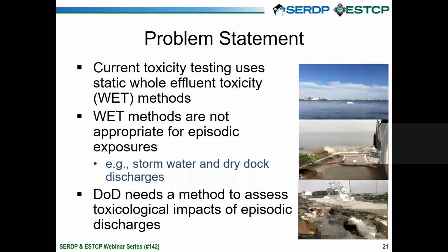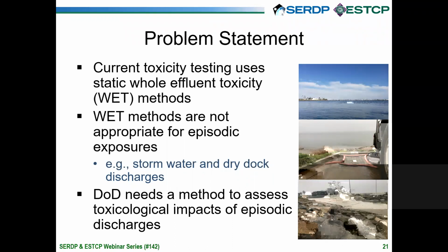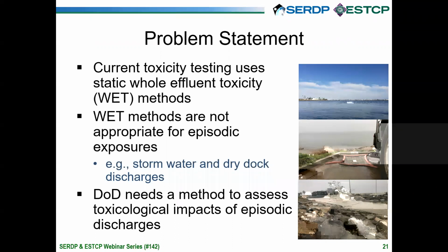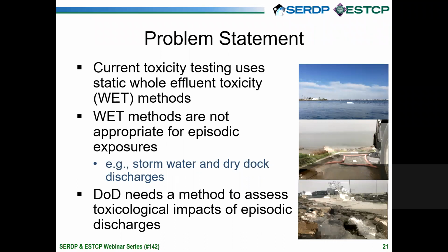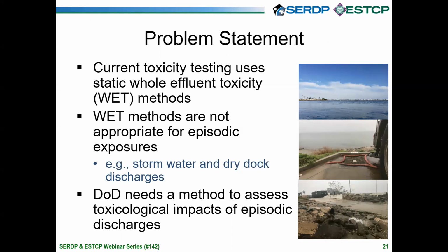However, storm events rarely last 96 hours, especially here in San Diego. And less than 24 hours later, for this example, sunny conditions were seen again. And the sample that was taken no longer is representative either at that point of compliance where the sample was collected, nor in the receiving environment. So the dynamic nature of stormwater discharges that might be experienced in a marine receiving environment cannot be accurately reflected using current EPA standard toxicity test methods.